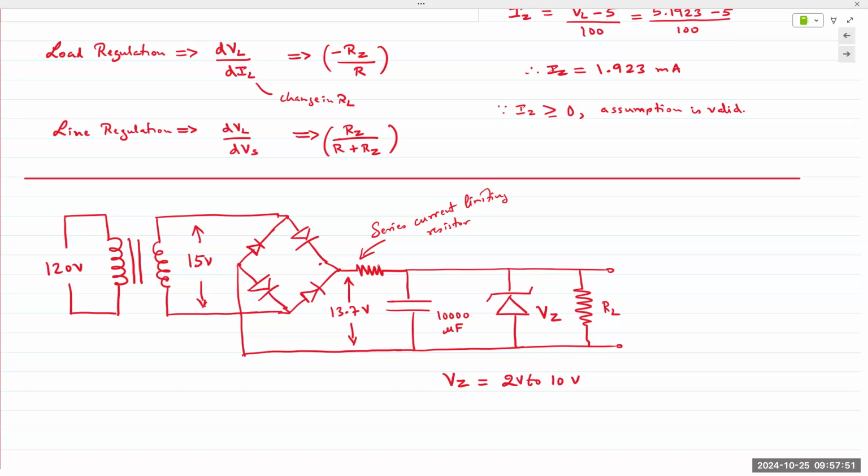Okay, so you have the rectifier circuits, you have the filter capacitor, and then we connect the Zener. The output of each stage leads us to having a near constant flat line at the output. And this is basically how most power supplies are constructed.